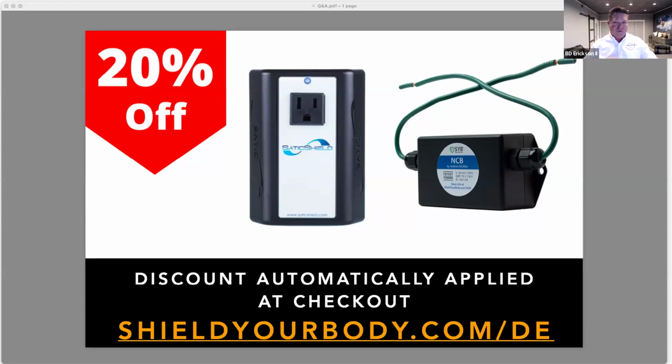We put lots of little filters in each one. And again, one should affect everything a little bit on that whole phase. So if we've got 2 bedrooms separated by some distance and they're both on A, let's say, when you put a good filter in one of the bedrooms, the EMI reading in the other bedroom will go down unless you're creating the EMI in that room. So that's how you can also know where your culprits are.